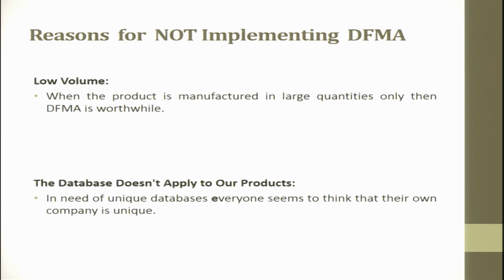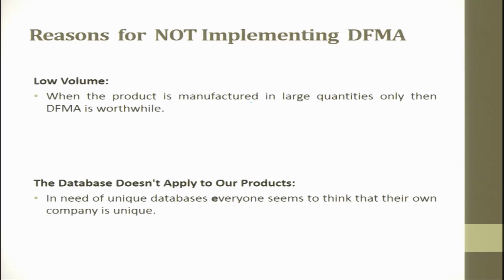If the production volume is low, then people also do not prefer going for DFMA, because DFMA needs a critical batch size in terms of numbers. When the product is manufactured in large quantities only, then DFMA is worthwhile. The database does not apply to our product. In need of a unique database, everyone seems to think that their own company is unique. So, this is the other reason why companies do not apply DFMA.